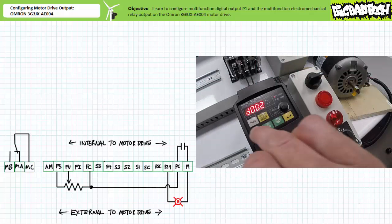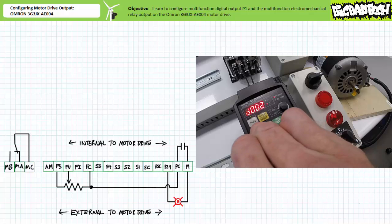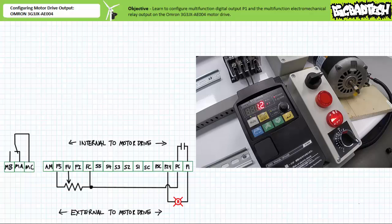Let's see the overload warning function in operation. With parameter D002, output current monitor, being displayed, when an operator presses run, during acceleration, whenever current is in excess of 1.1 amps, the pilot lamp executing the overload warning function illuminates. When in constant speed mode, the pilot lamp flutters on and off as current vacillates around 1.2 to 1.1-ish amps.